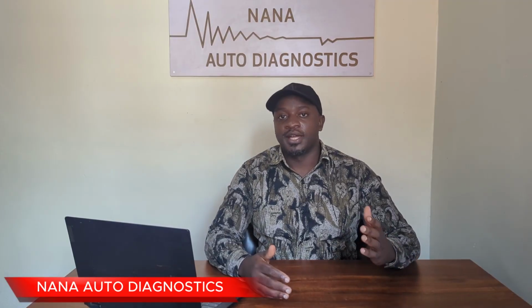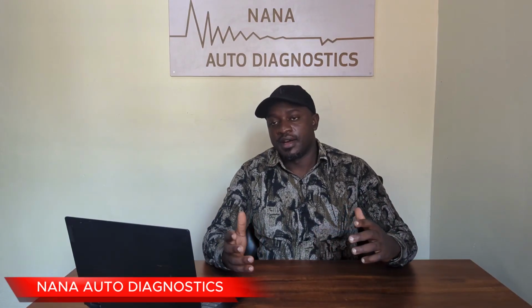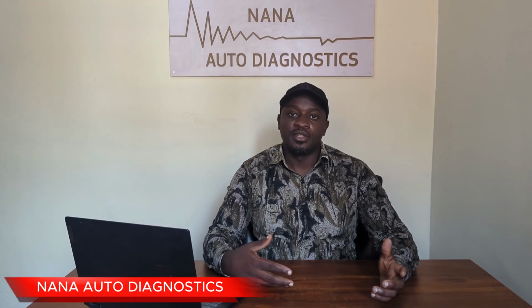I've already covered the J1850 communication protocol and the K-line in the previous videos, and I will tag the links in the description below. For CAN, we shall look at that in our next video. So whenever you are going to diagnose any issue regarding LIN, just know it will be a waste of time to start checking the DLC because you will not find it there. You have to go to the exact module where the fault is happening and start your diagnosis from there.